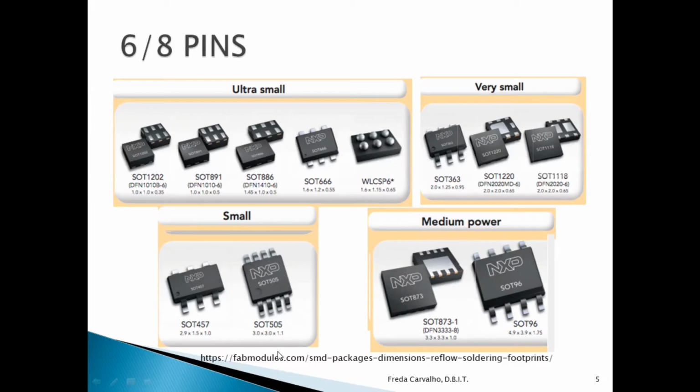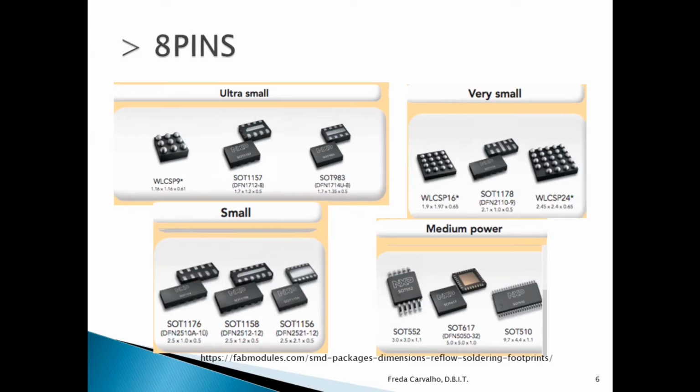You can see a lot of them, and you notice that they are not through hole packages. That is to say that these pins are not long to get into the boards. They are not meant to be that way. They are to be soldered onto the surface on the same side, so the leads as well as the surface of the chip remain on the same side of the board. Similarly, you can see how some pins have their leads on the opposite side of the surface of the chip. So soldering is another problem. This is definitely not meant to be soldered manually.